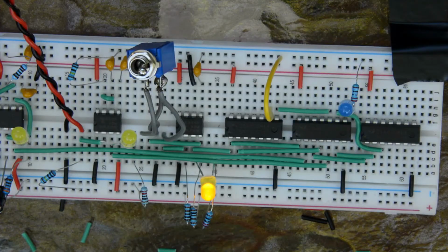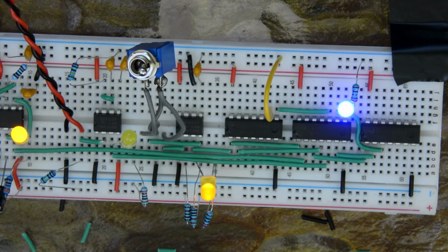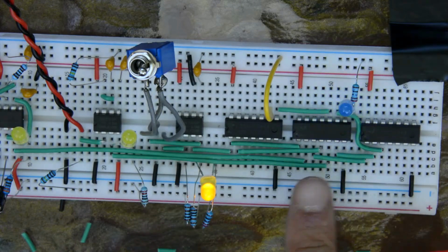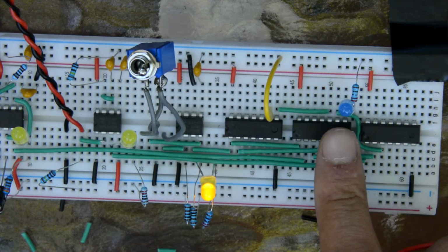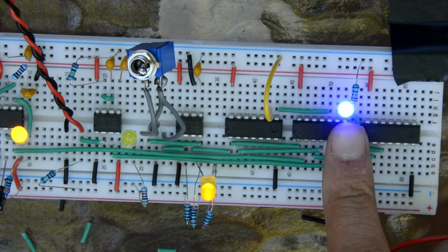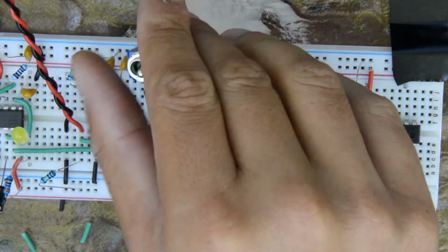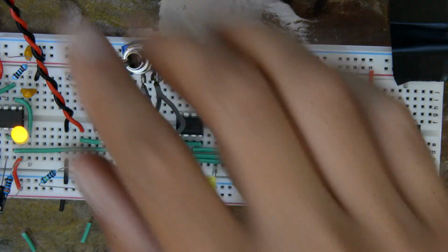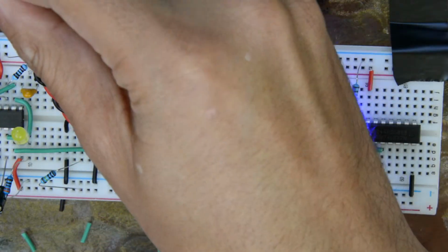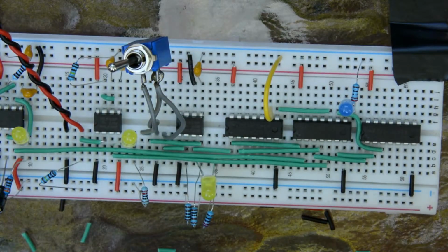Okay, this is Ben Eater's clock module, and it uses 3 555 timers in different ways, and then a couple of logic gates to combine the outputs here so that you can control your computer with a clock in 2 different modes. The 2 different modes are selected by this switch, so now the output of the clock is off, but there's a button here that lets me step the clock so that I could manually step my computer forward.